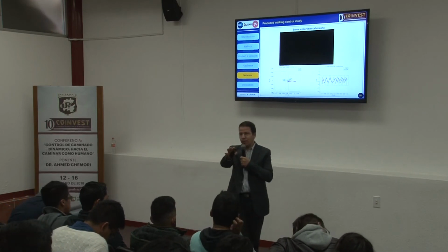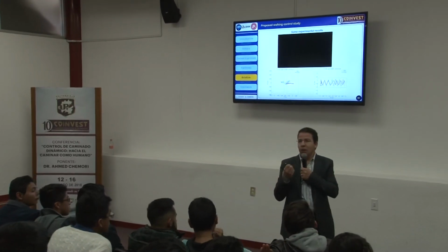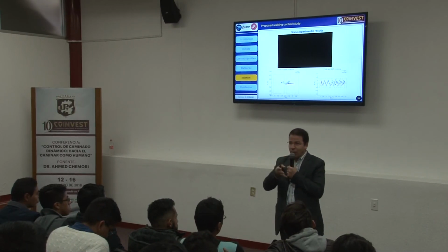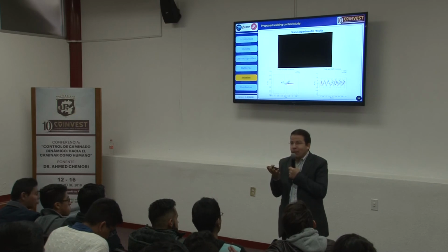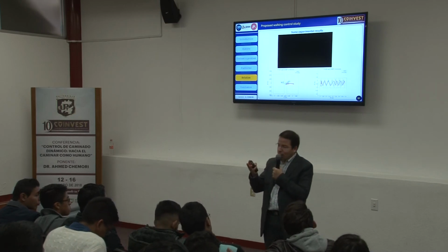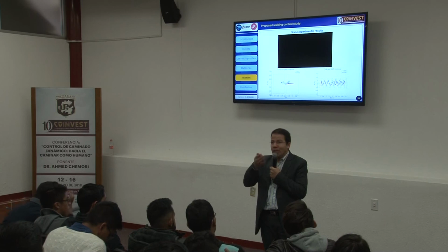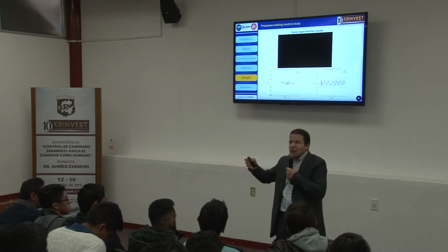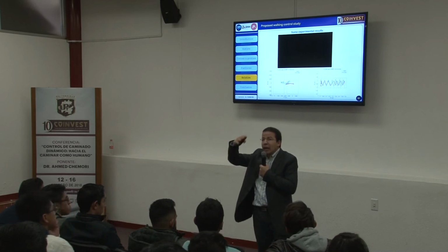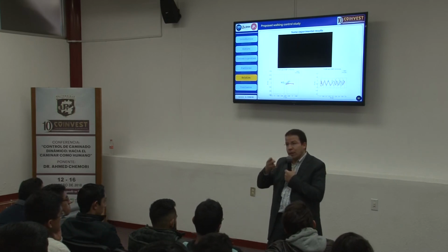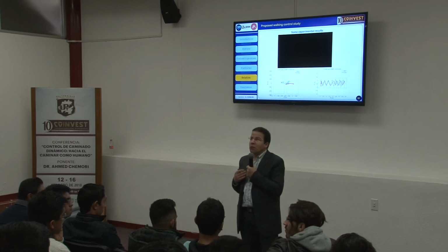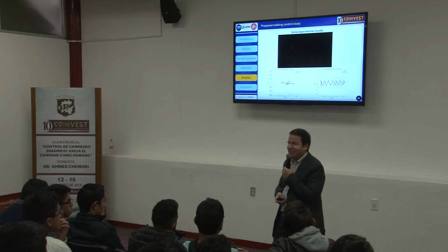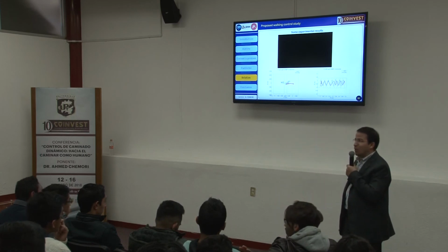This is very challenging. In the underwater vehicles, the problem is the uncertainties on the parameters. We cannot know everything in the parameters, and the time varying aspects. Buoyancy, inertia, many parameters can be time varying. And if you keep the controller as it is, you cannot keep the same performance unless your controller is adaptive or robust enough to deal with this. So concerning the complexity, I think it's maybe the same. Yes. Any other questions or remarks or comments?